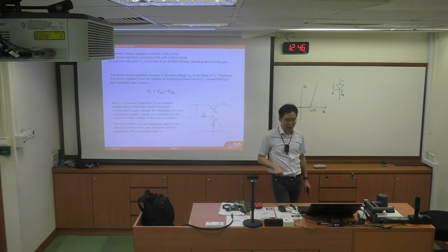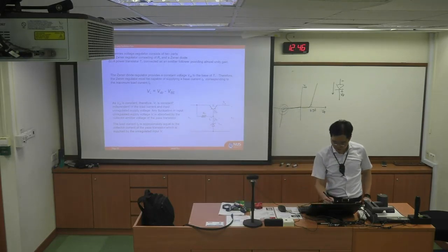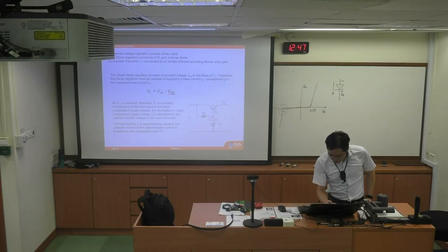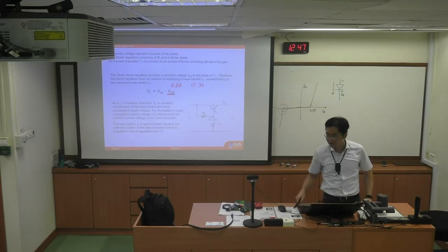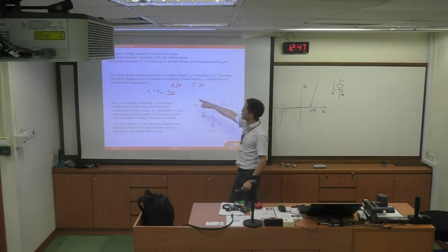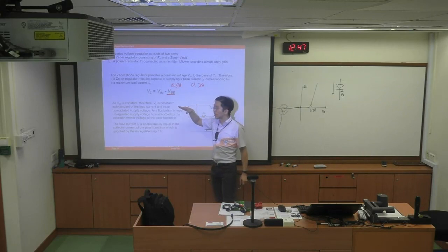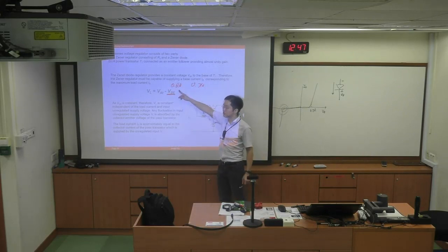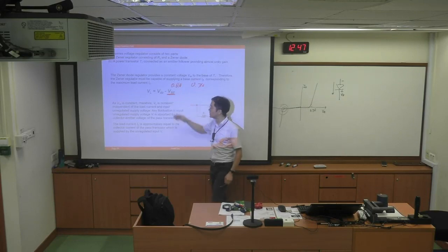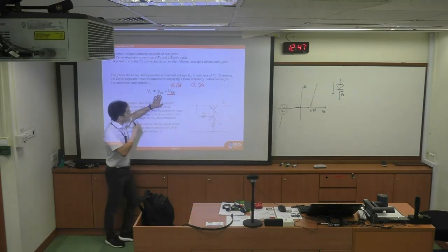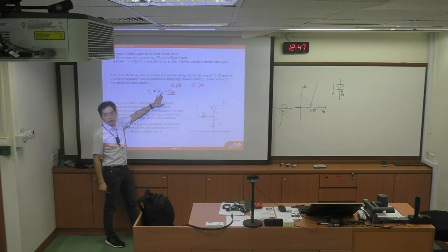And this is the regulation factor, so this will be constant. Why? Because VBE is almost always 0.6 volt for the power transistor, 0.7 for a normal BJT. Although it has slight fluctuation over temperature and the load current, it's nevertheless almost constant at 0.6 for power BJTs. And VDZ is also almost constant. That's how the Zener diode is made. The reverse bias breakdown voltage is almost controlled.